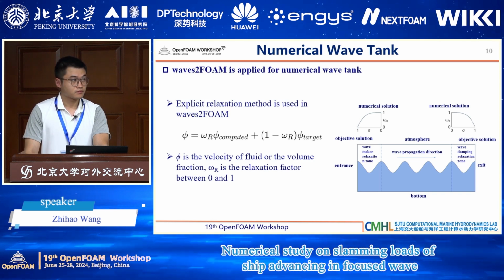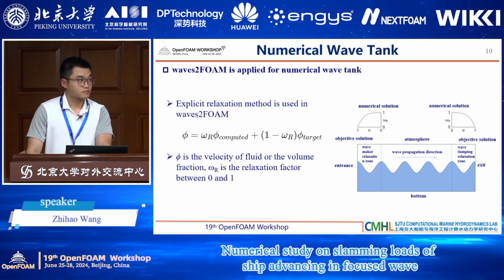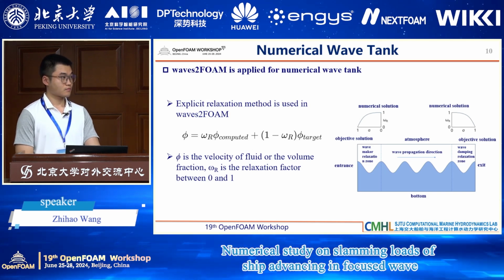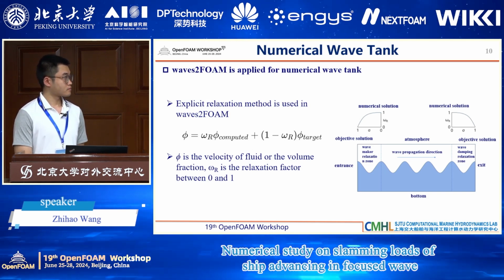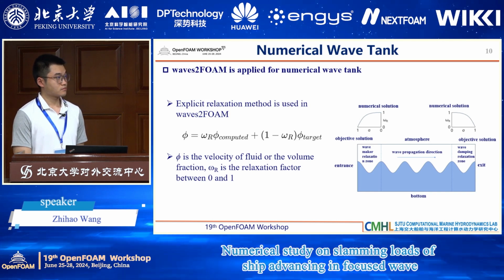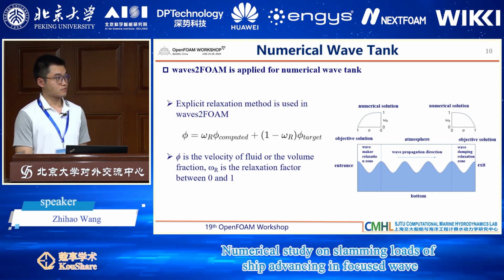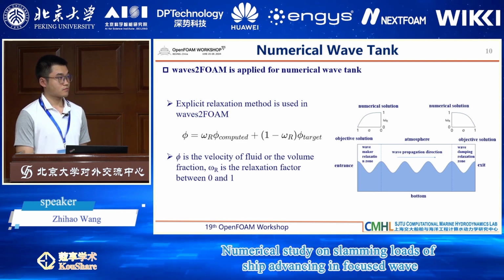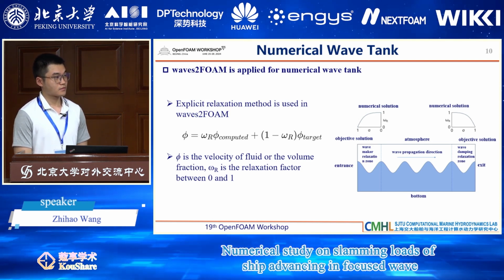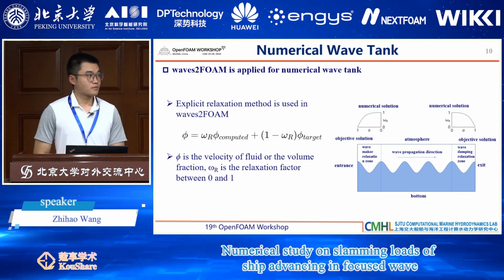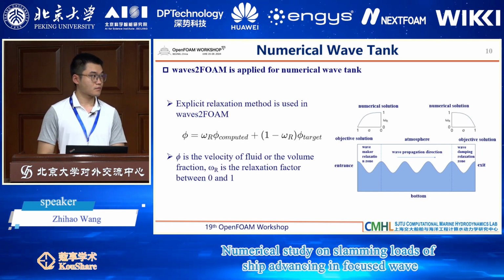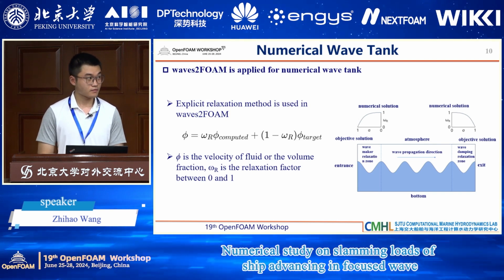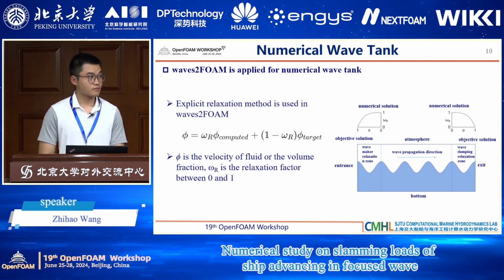Okay, so you have two benefits. The first one is that the precision of the shape of the wave is much better, and the second is you don't have to have the CFD simulation of the wave tank in order for the focused wave to develop from the motion of the body. So in CFD, we mostly use wave relaxation techniques because they are compatible with the way that the simulation is done. Does that answer your question?